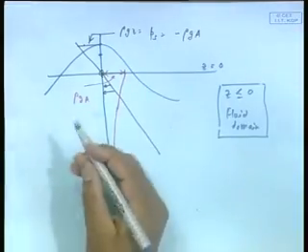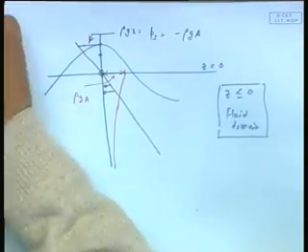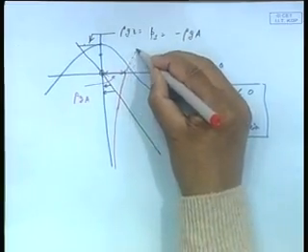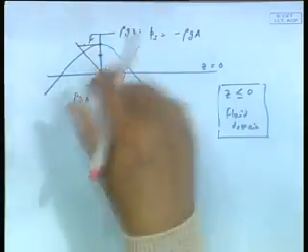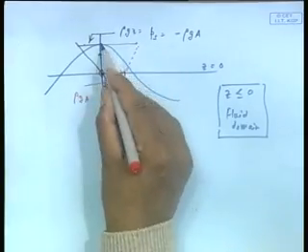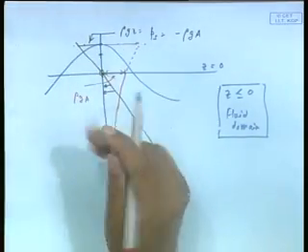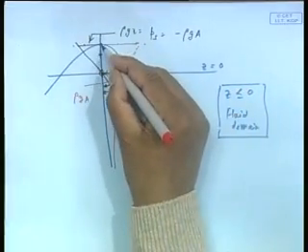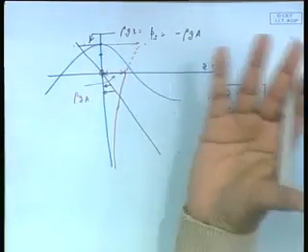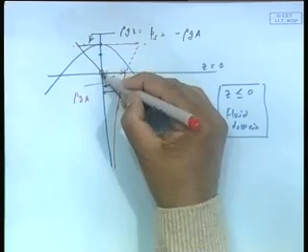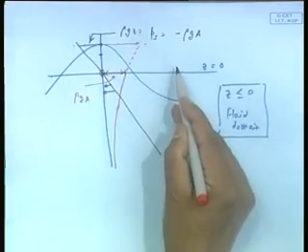So, now if I were to add the dynamic pressure, there is also a problem. Supposing I add dynamic pressure, so I apply this formula. So, what would happen? It goes like that, z e power of k z, z equal to plus 1 whatever. Now, if you look at this point, what would happen? This obviously is more than rho g a, now this is rho g a. So, this will end up getting some pressure. That is not correct because my pressure at this point is supposed to be 0. Where is the anomaly? The anomaly is because in developing linear water wave theory, what we have said is that this height with respect to the length is very small.